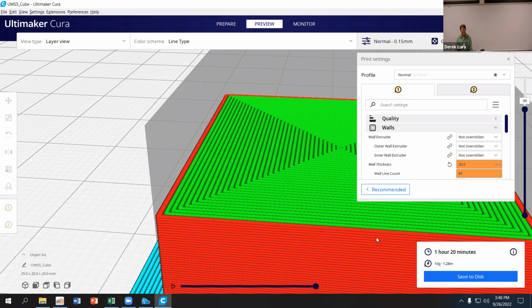Physically, you can see we have, this is a 10% infill, 20% infill, 30%, 40%. Actually, I think I'm missing one. I think this is actually 40, 50, and 60% infill. So you see that as I get close to 60%, it's almost getting to the point where it's pretty solid, right? I think all these actually have 3 walls. These parts are pretty strong, right? Having a part like this with 3 walls, I don't need any infill on this part to hold the structure, just because it's not that large of a volume.